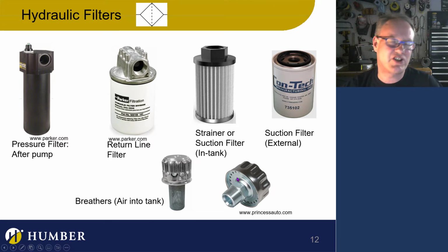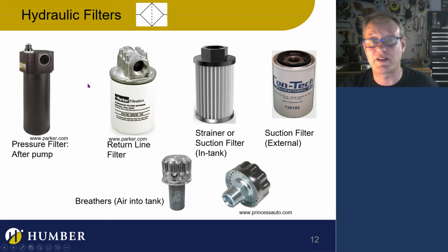And yeah, there's just a certain amount of filtration in there. It's not a lot. It'll be just like a metal mesh or even a cotton mesh. Something that is just like a breather in the pneumatic systems, where we were talking about breathers. I've actually seen these that are fiberglass, with a fiberglass mesh in there. So essentially, it's easy just to replace them. Often you just grab a new breather and put it in, but some of the breathers you can take apart and actually change the filter material that's inside there.